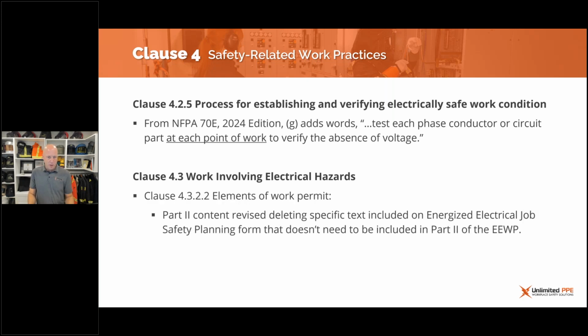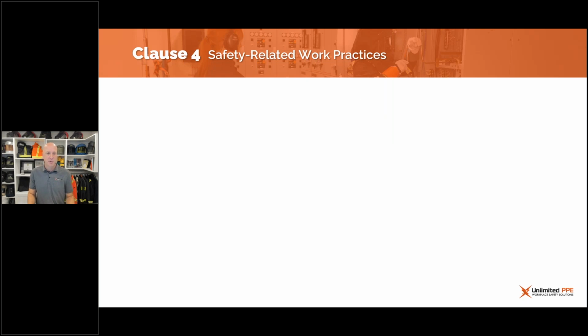Additional elements of the work permit. So we added content revising that the energized electrical job safety planning form doesn't need to be included in part 2. So there was overlap between some of the pre-job briefing and planning requirements and the energized electrical work permit requirements. So we've cleaned that up in 2024.